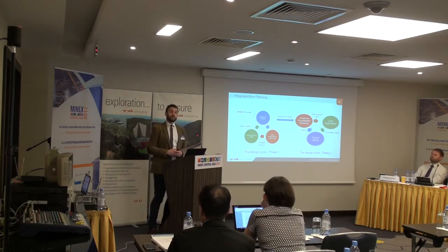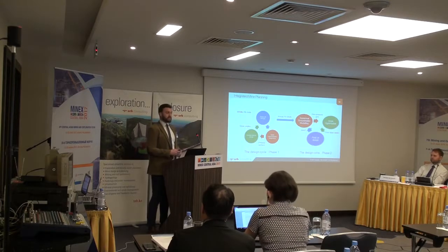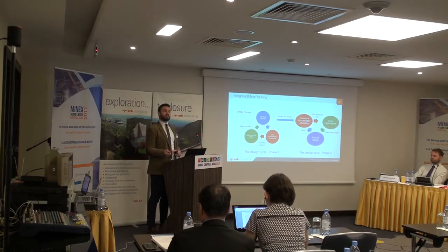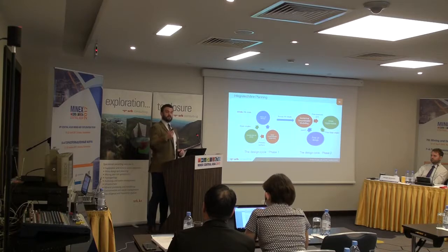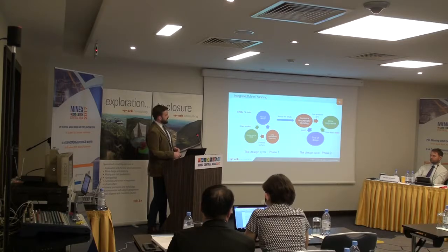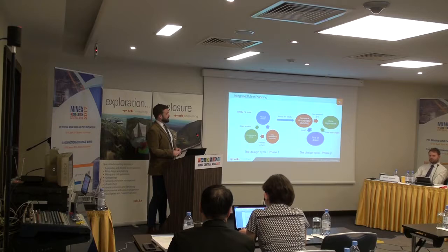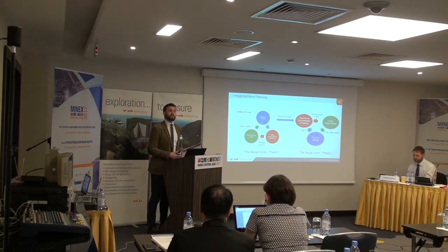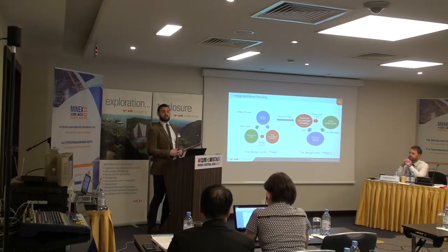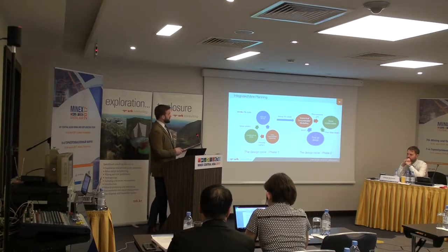They would then carry out detailed numerical modelling to understand the impact of the mining on the groundwater level over the life of mine. And it's really only then that we get a more realistic understanding of the groundwater conditions for our slope optimization. And we would input then the pore pressure grids to really try and optimize that slope to give the steepest permissible slope angles for the design.